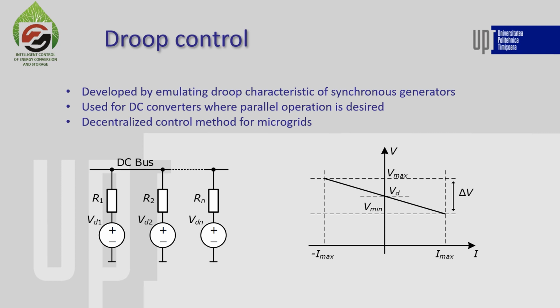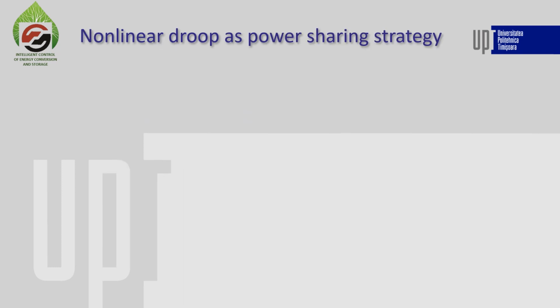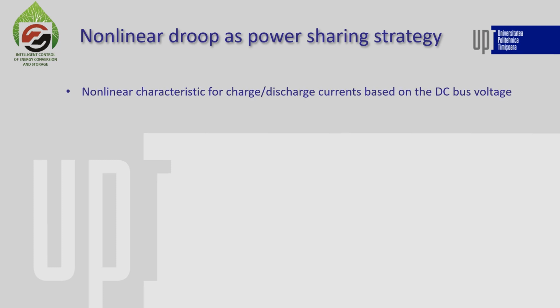Again, it is important to remember that the resistive characteristic is implemented in the control strategy, and it is not an actual resistor connected in series to the converter, as that would greatly increase the losses. This next section presents two different power sharing strategies for supercapacitor storage, with a simple or more complex implementation that are decentralized and based on the standard Droop control method.